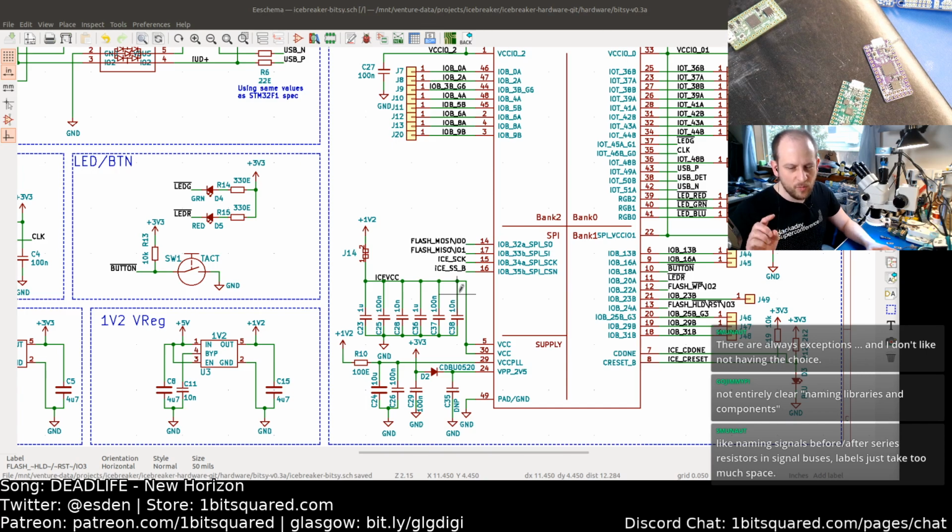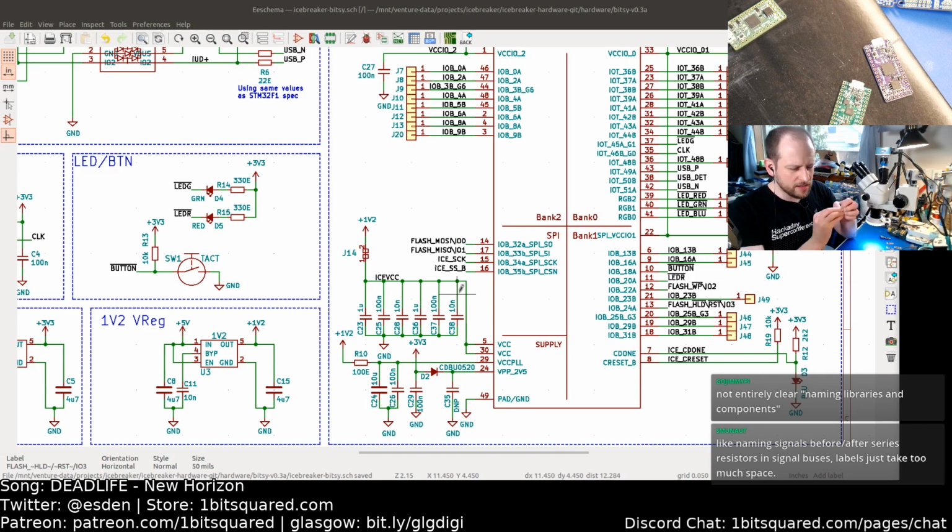Yeah. So what you pulled up, Jimmy, is the library convention, but that also impacts. So I know that if you have a pad or symbol connection and you don't give it a net name, it sometimes uses those as a naming for that net.